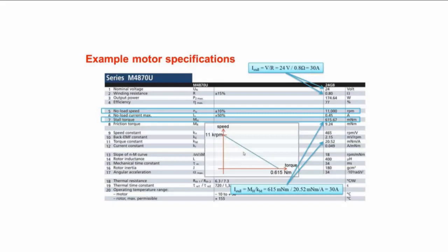So if you want to calculate your battery capacity, please focus on this: not output power, input power is important for us. If the efficiency is, for example, 70% and the nameplate says 200 watt, actually your input power is 300.